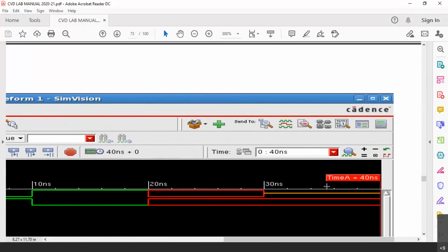Now lastly we gave z. Z is neither 0 nor 1. You can see it is in between. It is VDD by 2. It is neither sinking nor sourcing that way. Then when it is z, output is x.